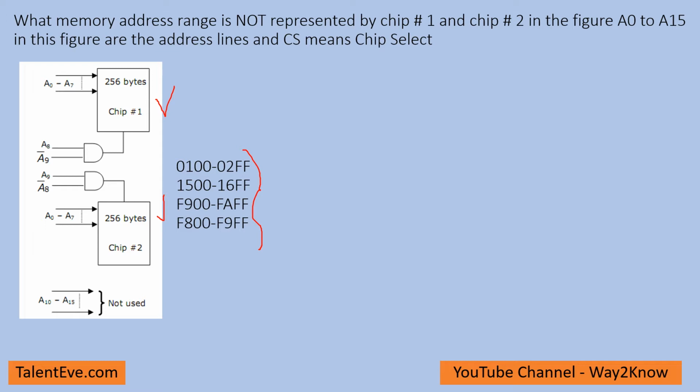So now, what we have to understand here is, if we address directly, for example A0 to A7, that is a byte, so you will have addresses starting from 00 to FF directly. So all the address range from 00 to FF will be represented by this, right?